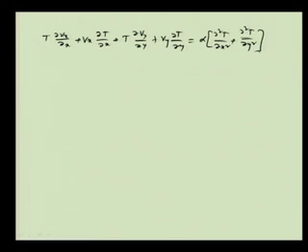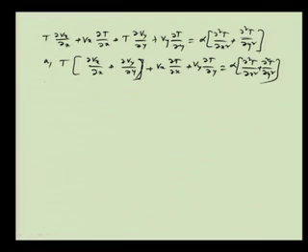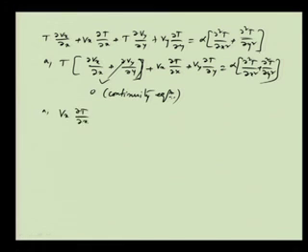So, now we have to do some application. So, you can write that T into (∂Vx/∂x plus ∂Vy/∂y) plus Vx into ∂T/∂x plus Vy into ∂T/∂y is equal to alpha into (∂²T/∂x² plus ∂²T/∂y²). Now, this part is 0 from the continuity equation. So, we are using the continuity equation also, even when we are going for the energy balance equation. Then we can get that Vx into ∂T/∂x plus Vy into ∂T/∂y is equal to,